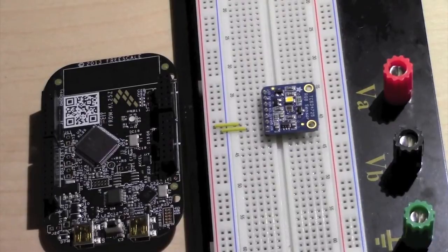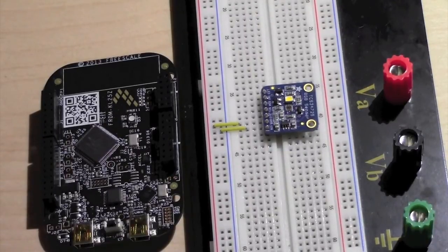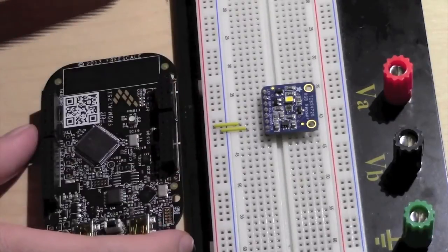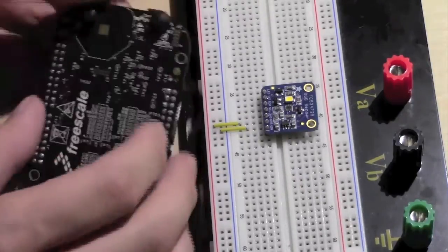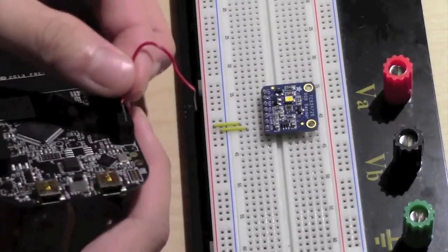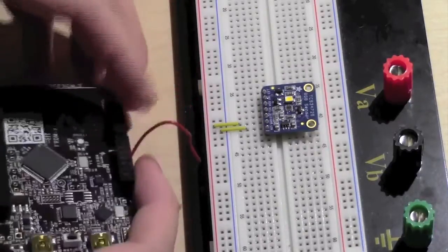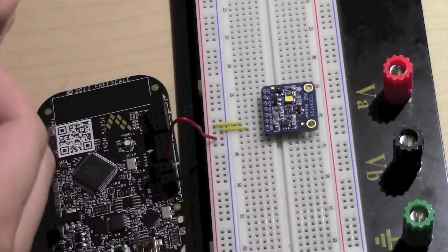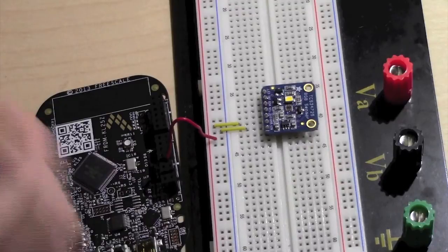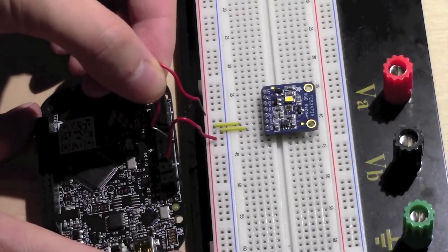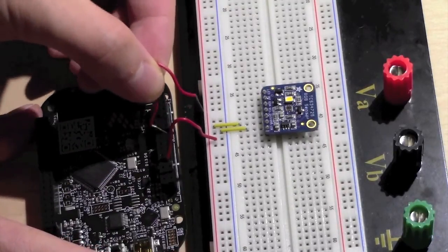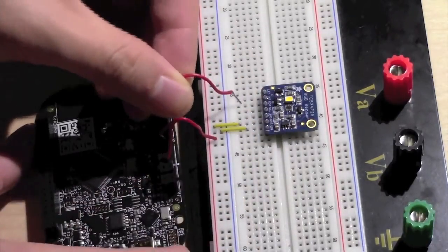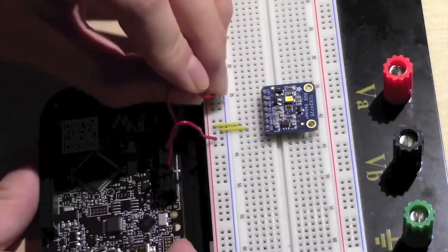All right, that should make it a little more organized, so we can connect the 3.3 volt line on here to 3.3 volts on this little power rail right here. Locate the 3.3 volts, as always it's the fourth one down, so 1, 2, 3, 4. This connects to the power line. Then we're going to locate ground, which is always right here, either one of these 2 pins, so either the second or the third from the bottom. We just connect that to the ground line right here.